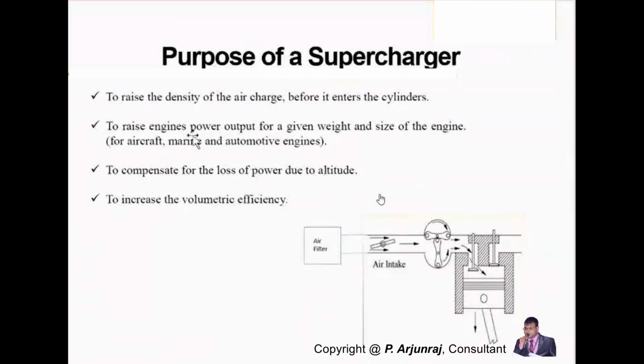And again, I told you we are going to increase the power output for the given weight, irrespective of, and it is also applicable to, the different sizes of the engine. And we are going to increase the volumetric efficiency. And again, you see, we are going to compensate the loss of power due to the higher altitude. This is the air which is coming into the system with the help of this supercharger. We are going to achieve all these things.